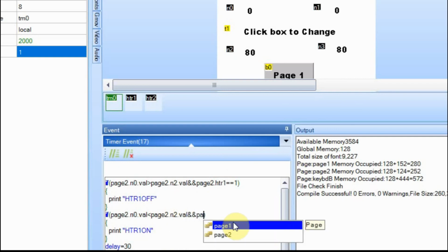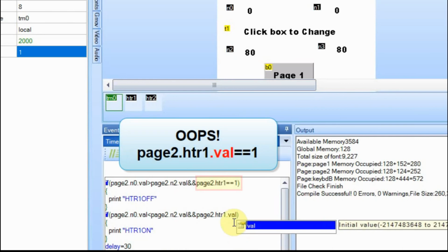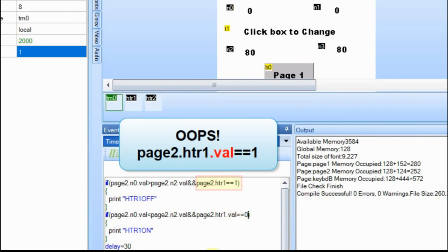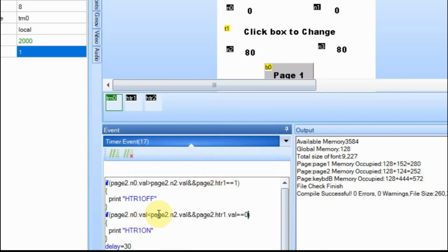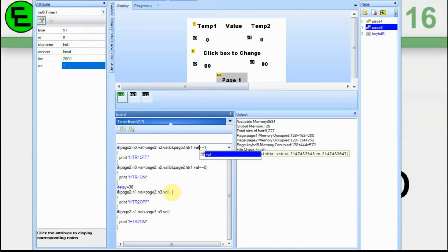The same goes for this down here. I have to put the value in this too. So in this case, if it's less than that, then we want to go ahead and turn it on, but only if it's currently off. Once it's on, then we don't have to do this anymore. So once it's on, we won't turn it on again. The logic can be a little backwards on this, but if you're willing to test with some LEDs, then you're fairly safe to do some samples and stuff. Then we have to do the same thing down here, but we'll use heater 2.